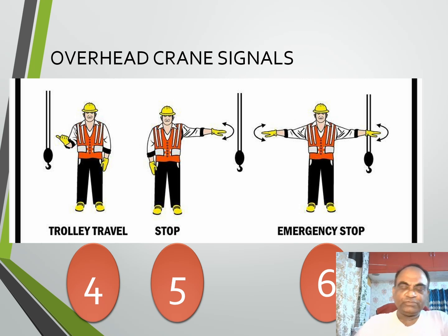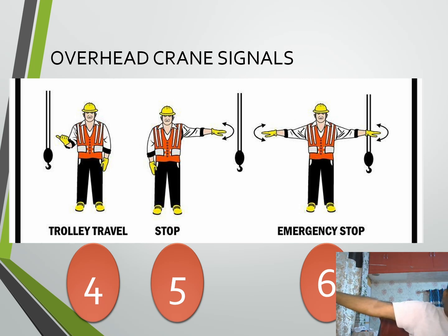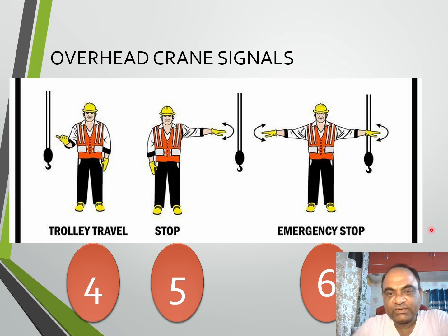And to stop the crane, you have to stretch your arm in the right direction. I'm showing you like this, and you have to wave the hand in this manner. Don't keep it still. You have to wave the hand up and down to stop the crane. In the case of the emergency stop, you have to stretch both your arms and wave them.